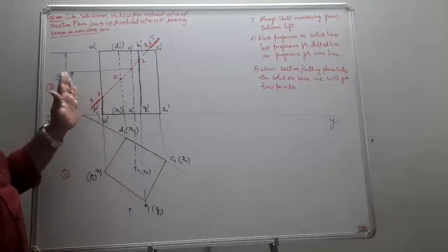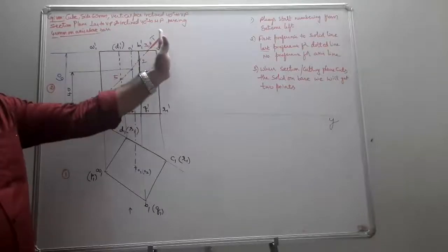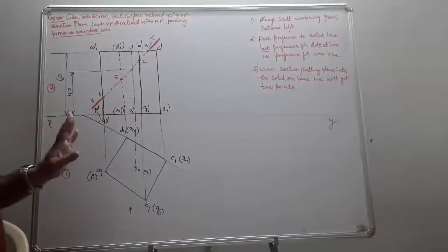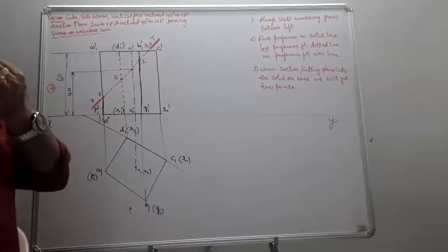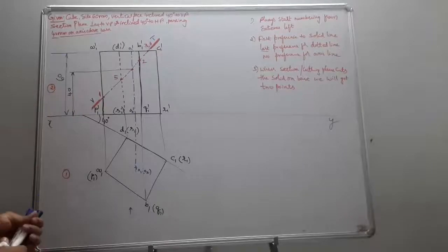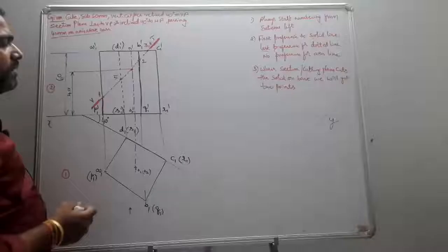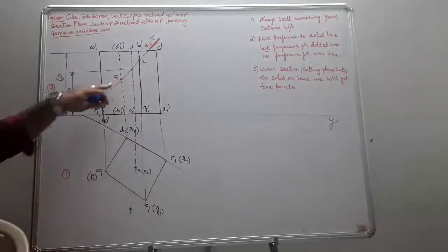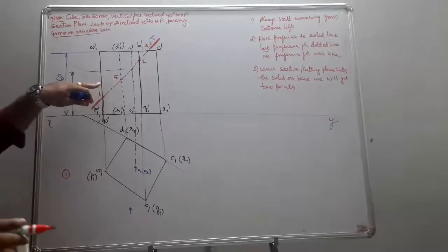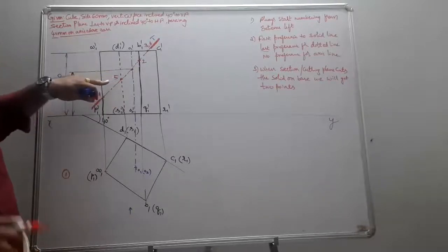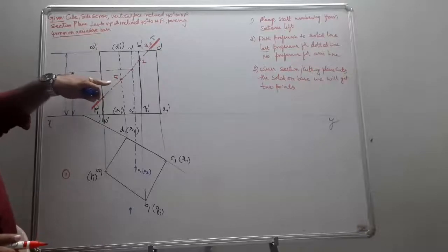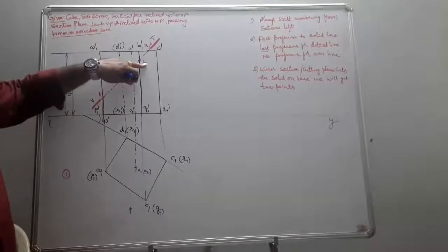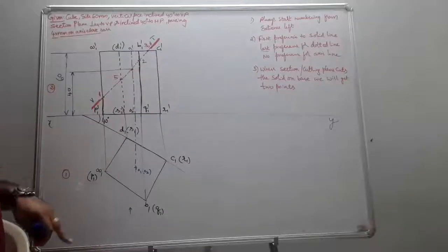Next, moving from left to right, and after the points are completed, you come from right to left, in this pattern, and again come to here. Whatever points are obtained, you just mark them. So this is one. Is the next point 2? No. Why? Because this was the dotted line, which is given the least preference. So I go for the next visible solid line. The visible solid line point is 2, that is BQ. BQ is the solid line.